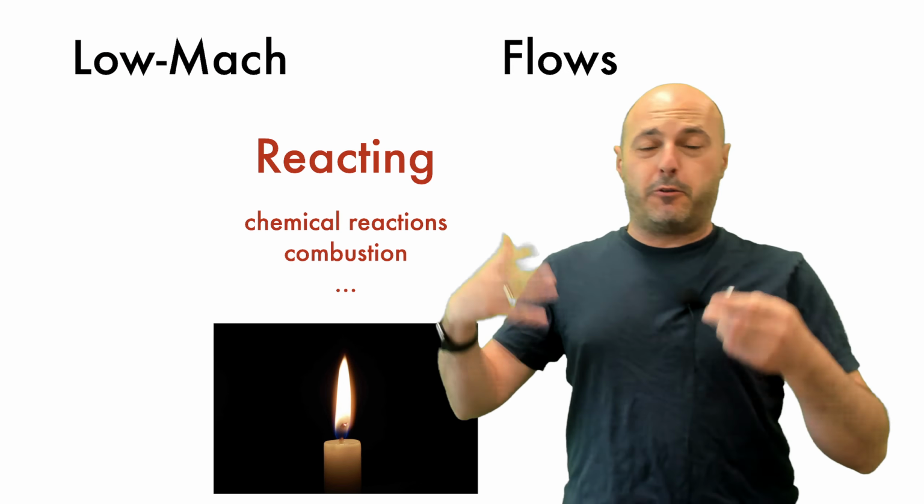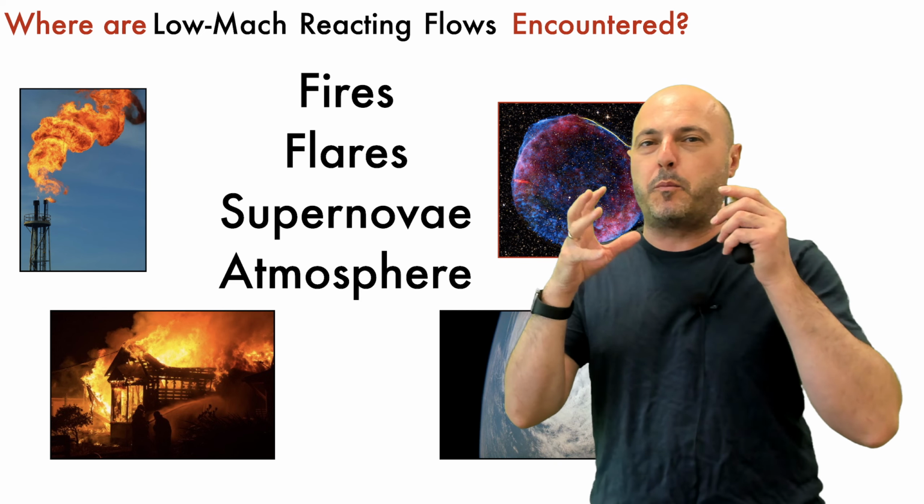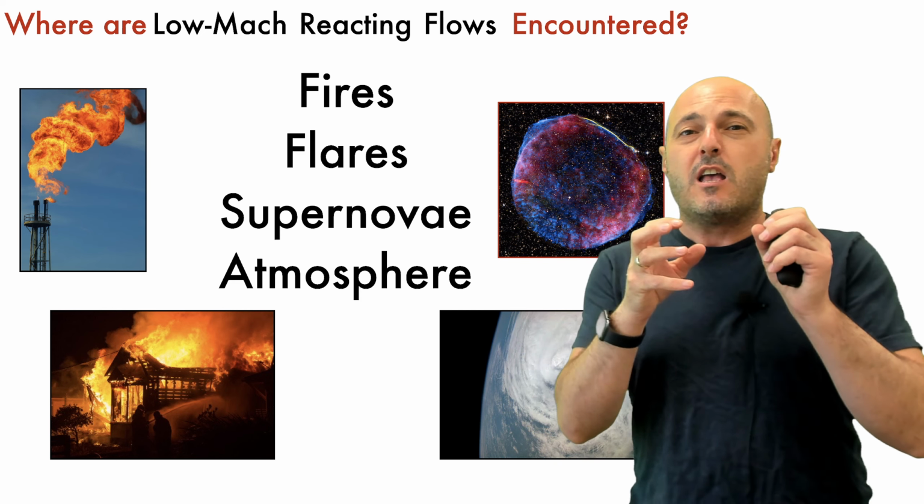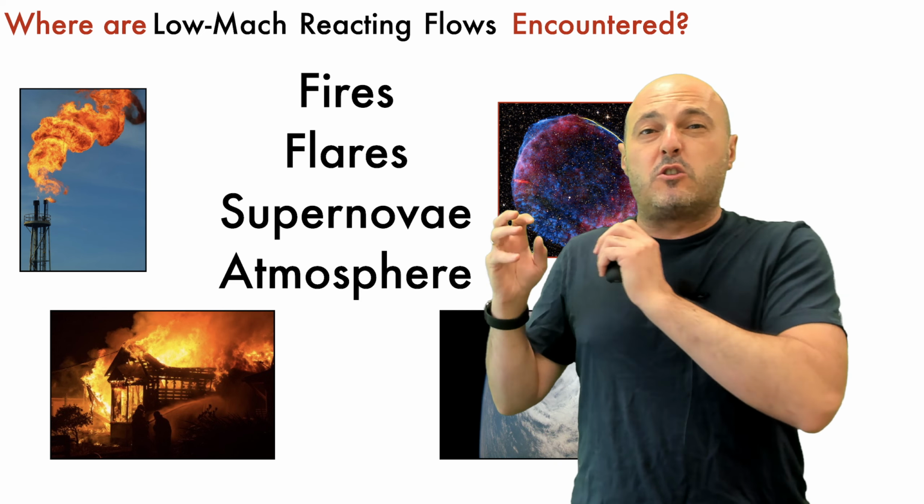So where density is loosely coupled to the pressure, or small pressure variations cause no density variations. Some big pressure variations might cause minor density variations, as opposed to true full gas dynamics where a slight pressure variation is going to cause almost the same density variation.